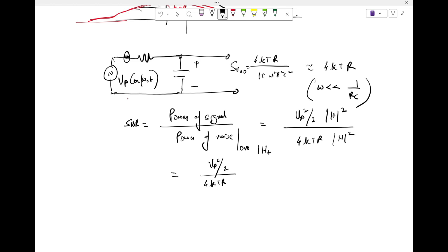If you simply add one resistance with the voltage source, you will see that as long as the resistance is much smaller than the R, then it's fine. But if in a quest of reducing noise, you keep on reducing this R, then that assumption will not hold true. And hence you are going to see a lot of drop across the voltage source terminals itself. Right? So that's a downside.